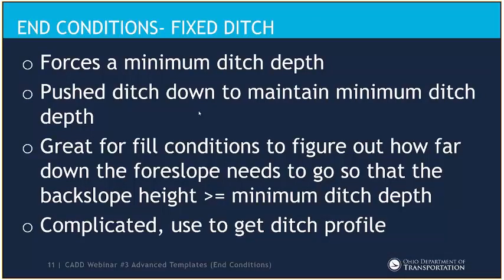So really getting into more of this advanced topic of end conditions is this fixed ditch or daylight ditch. It basically is going to force a ditch to be drawn in, and that ditch will be at least the minimum ditch height that you set. Think of it as pushing the ditch down and out more until it can actually solve.